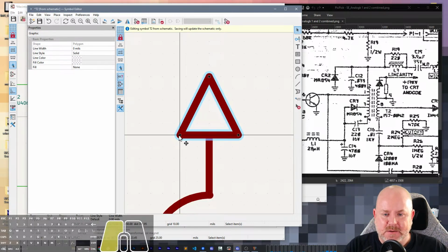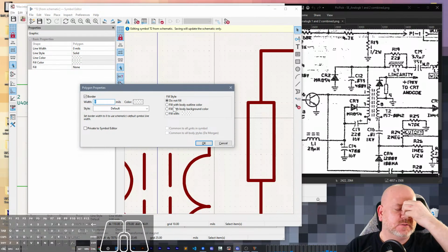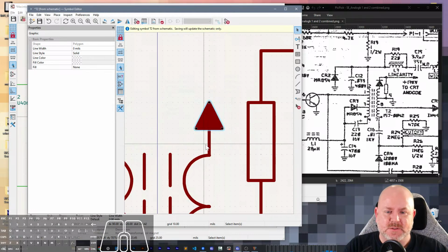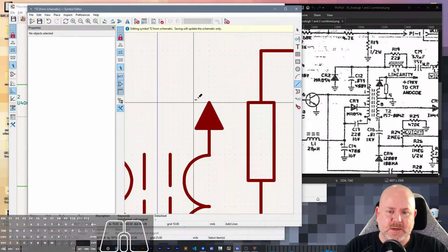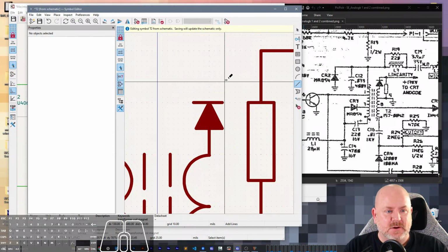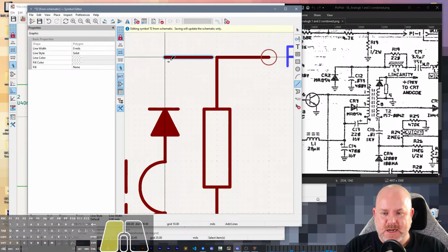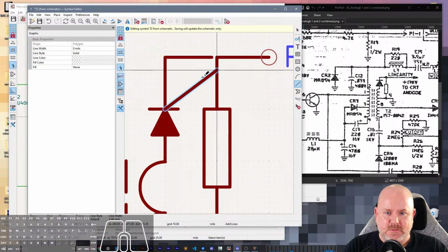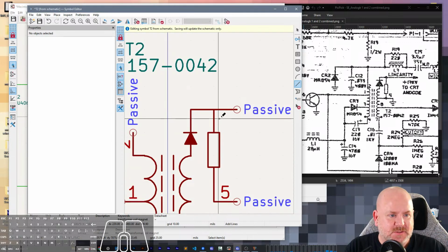So I ended up buying switch mode power supply modules on Amazon that had the same chip, because I thought, all right, we'll take the chip out of here and put it into the power supply, and at the very least I'll be able to see if this is the problem. Anyway, I was trying to remove the IC from the little breakout board using hot air, and while heating it up, the big electrolytic next to the chip exploded in my face.